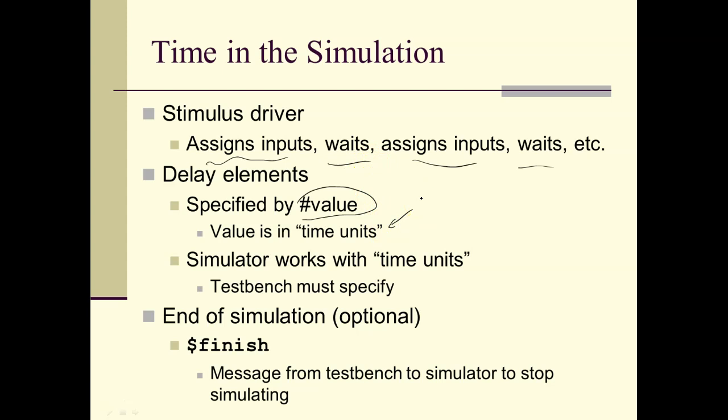Anytime in a simulation, the test bench itself will define exactly what those time units are, whether it be nanoseconds or microseconds, etc. But that's something we generally don't do. The tools kind of do that for us. If you need to change it, it's pretty easy to change. It's essentially like a line in the model. So there are the delay elements. The other thing is the keyword finish. It's a message from your test bench to the simulator that, hey, you're done simulating. You're going to stop your simulation.